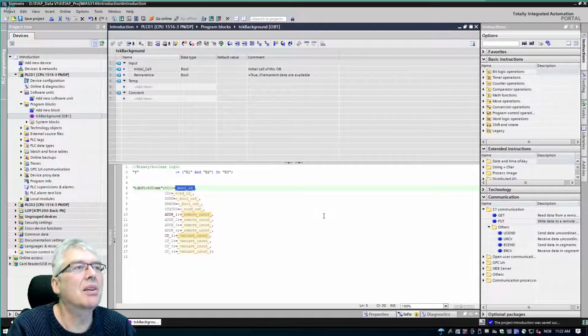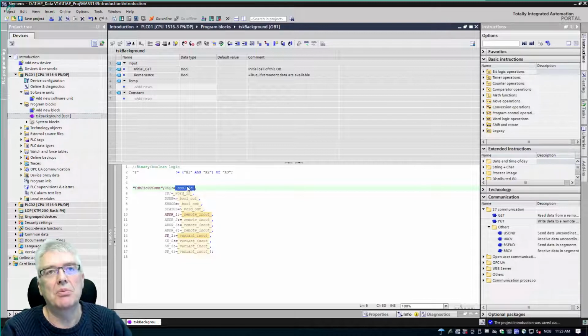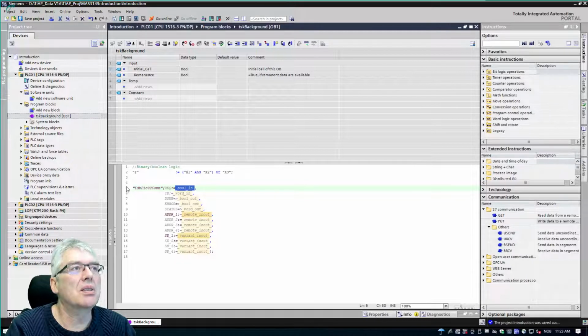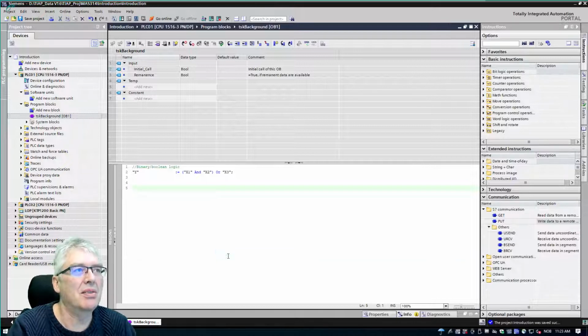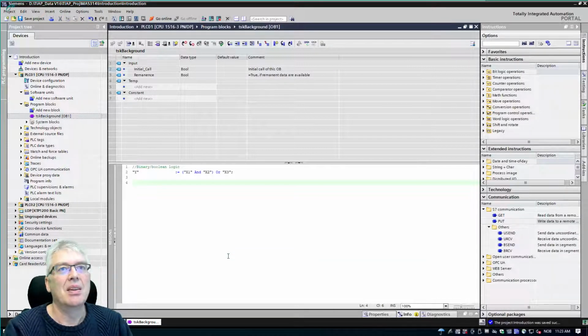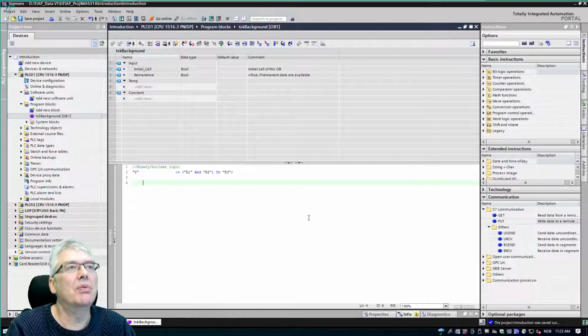Now I'm just going to leave it like this, because here you have to program this, and you have to find this information, so connection resources and how to communicate, and the REQ request. If that changes from 0 to 1, it just transfers the data. So this is more complicated, so there is programming involved. I'm just going to delete this one. So okay, there is programming involved if you want to communicate between the PLCs.